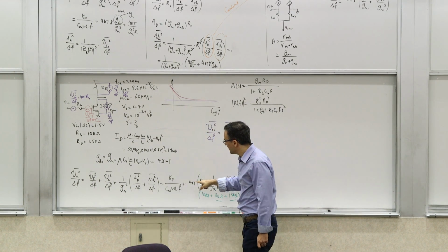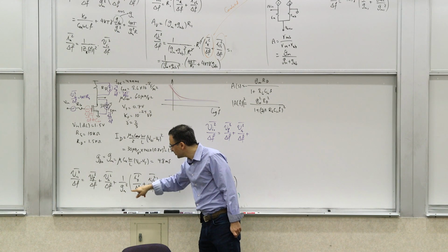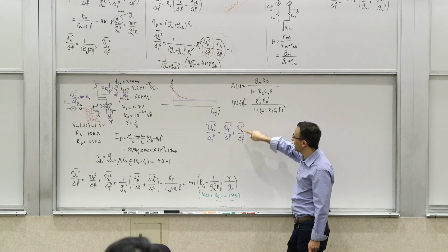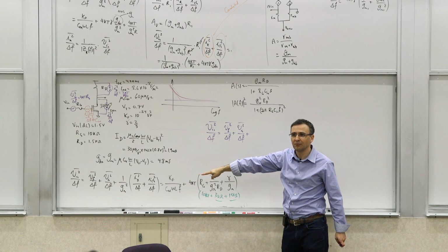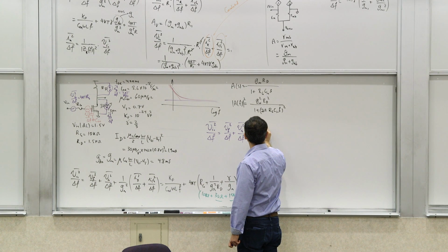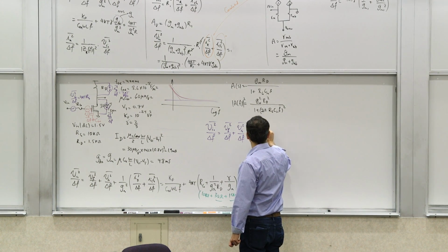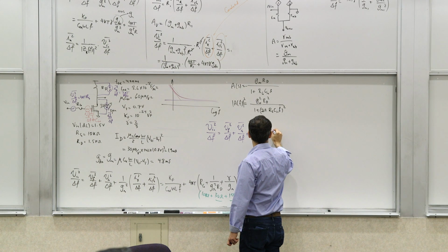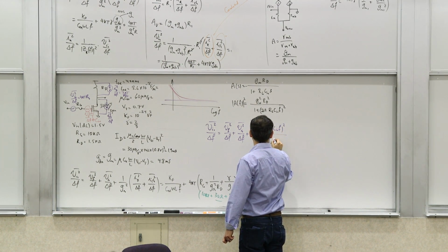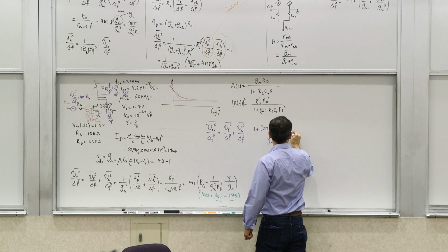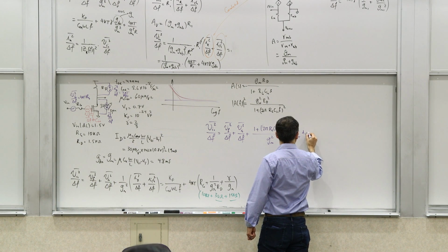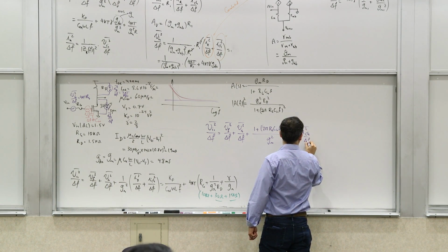But now these guys, you still have the GM squared, but now you have to divide by that. So when you divide by that, this denominator will appear in the numerator, right? When it's referred to the input. So what you will get is 1 plus 2 pi Rg Cin F magnitude squared divided by Gm squared times those two. You agree?